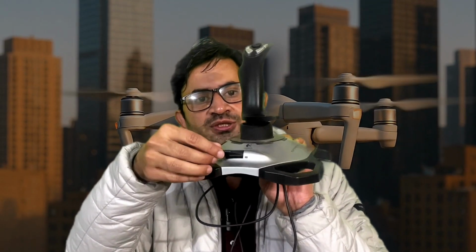So this is the stick I have, a Logitech stick, and I will map it like this. For example, if you are giving the left roll, the phi command will be generated. Similarly, in this case negative phi, this positive phi, and this forward negative pitch angle, positive pitch angle, this positive psi, negative psi, and this one is throttle, idle position, maximum position.